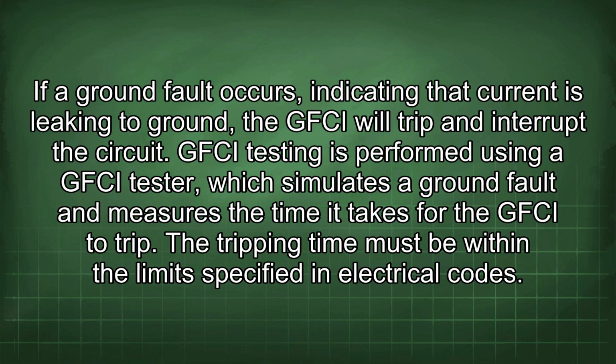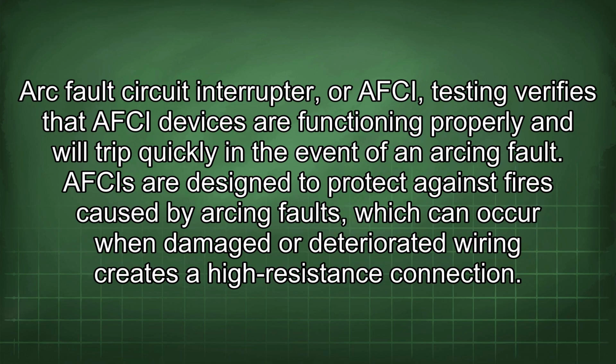GFCI testing is performed using a GFCI tester, which simulates a ground fault and measures the time it takes for the GFCI to trip. The tripping time must be within the limits specified in electrical codes. Arc fault circuit interrupter, or AFCI, testing verifies that AFCI devices are functioning properly and will trip quickly in the event of an arcing fault.